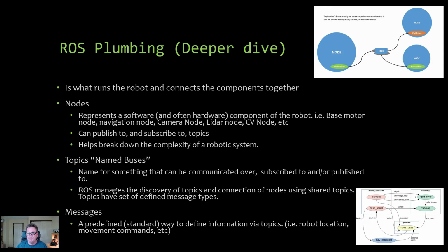So it makes them independent of the hardware. Some bases walk on legs, other bases have tracks or wheels to move the robot around, but they all want to do the same thing of moving the base a certain amount, and the standard command velocity message can be read by all the nodes that are subscribing to that movement topic.